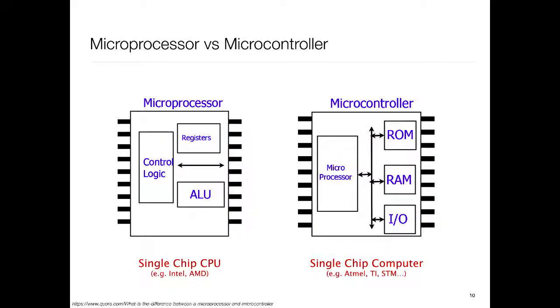The challenge they face is that when you are working with microprocessors and your memory is separate, your memory could be designed in a silicon process optimized for memories like DRAMs, and your processor in a process optimized for that. Here, the same process has to handle everything. So you would normally not see DRAMs out there, because DRAMs are designed using very different processes, which are not the digital processes.